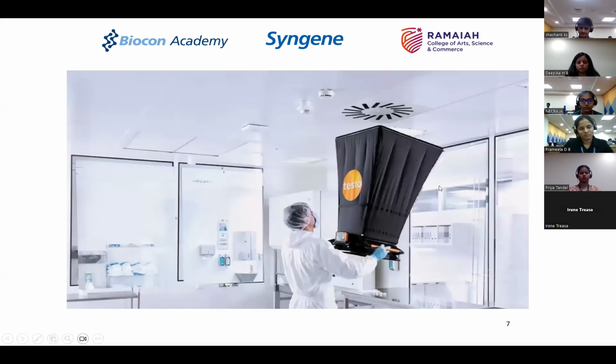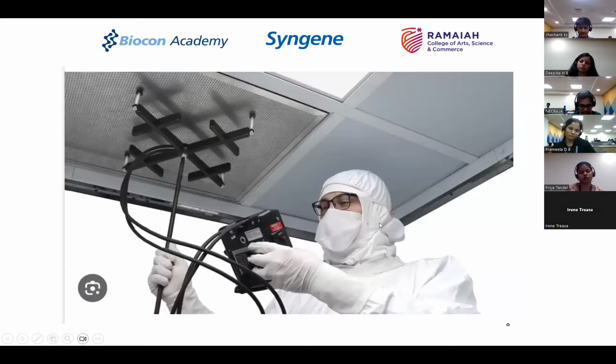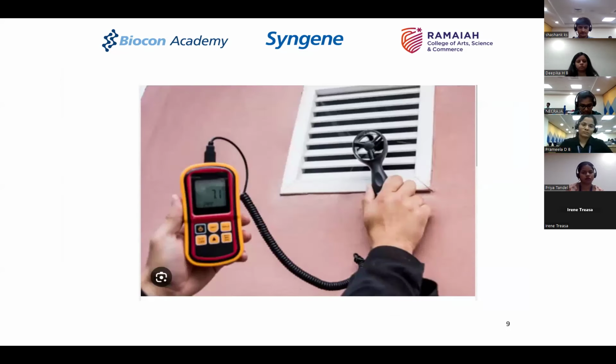Whereas if you go with such a hooded type, now it's all digital. If you place this particular hood and enclose this area tightly, then whatever air is pumped into this hood will be going out through the measuring station here, and accurately you will get the data on this particular screen. That will be noted down. In the same manner, they will be taking readings at the return air grills also.